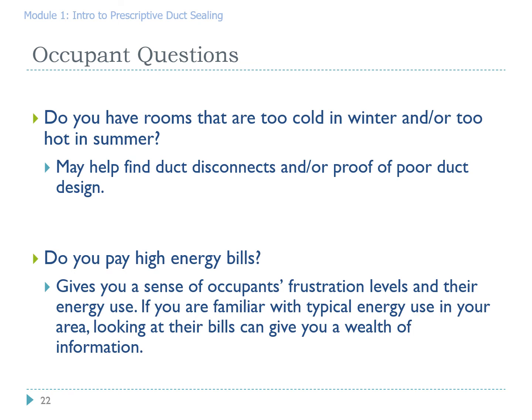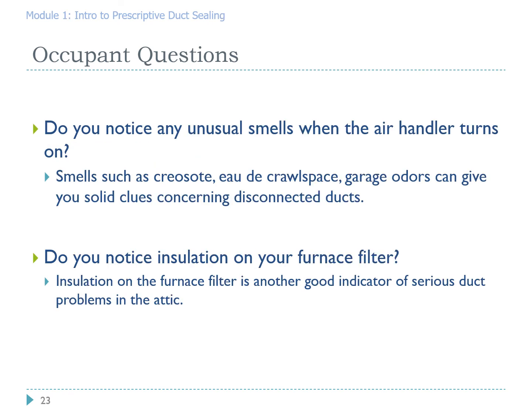Ask if they pay high energy bills. It's been my experience that people who have high energy bills, or feel that they have high energy bills, think they're paying a lot for the levels of comfort that they're actually getting. So do pay attention to that question. That level of frustration they have with their energy bills could be a sign that they have a really leaky duct system.